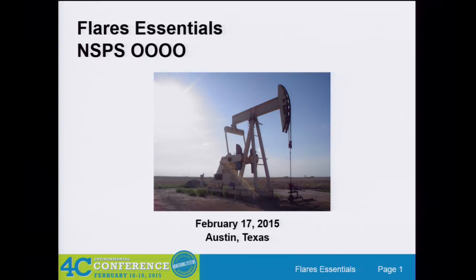I can drive up and down the ship channel and see tens, if not hundreds of flares where there are no flames present. But now you have to ask yourself today, do they have flare gas recovery? Do they have a water seal? Are they really not using their flare? Or potentially are they oversteaming it?